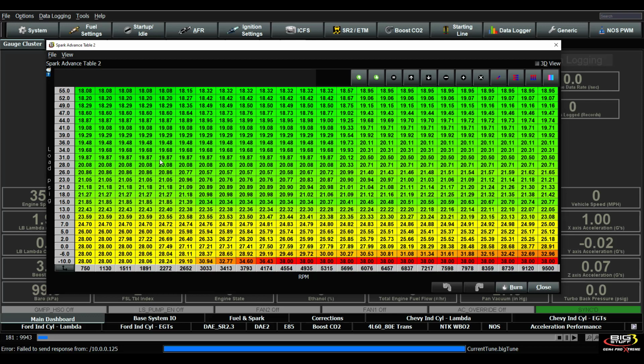So when you switch on the duty cycle, you're nowhere near that low RPM and nowhere near that low of boost or engine vacuum. So you can increase the resolution if you want as well too. That's why you have the adjustability there on the X and Y columns.